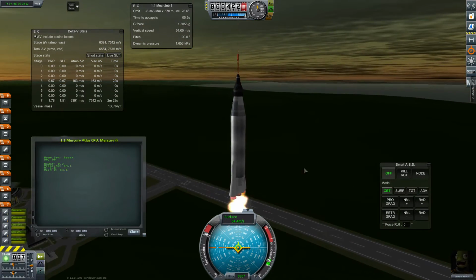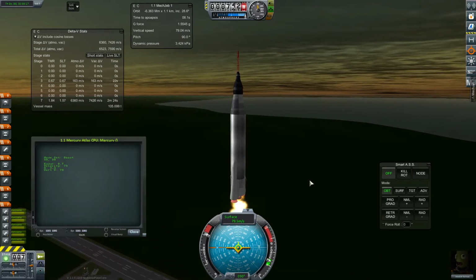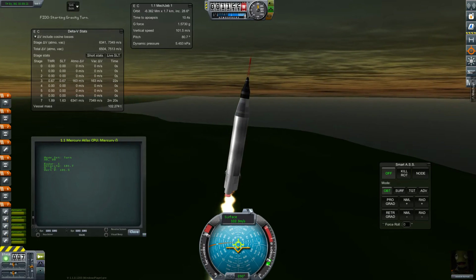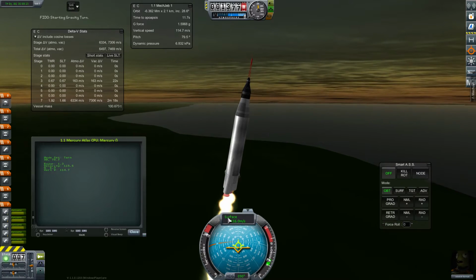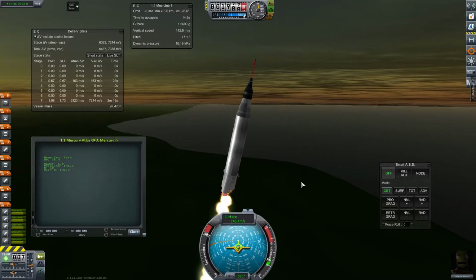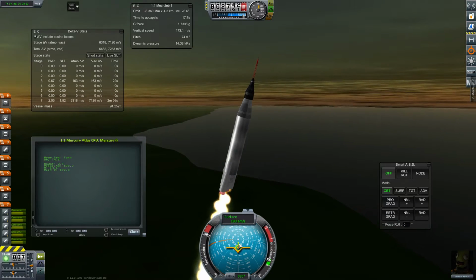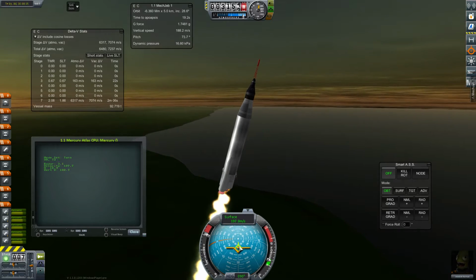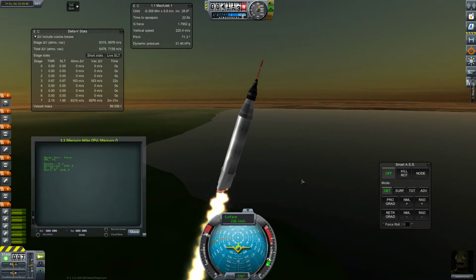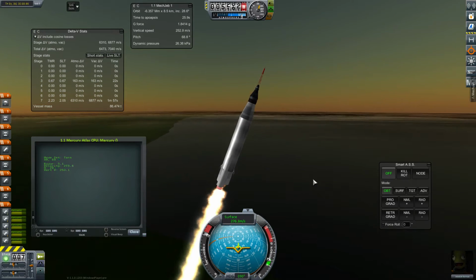It goes through a number of phases, and I'd like to get it down to two main phases, but there are always going to be these early phases, like straight up boost, and then the code has a line where it says, once you hit this speed, start your turn, start the gravity turn. From what I can see, the gravity turn doesn't have an equation directly, so it doesn't have a way to compare to your surface prograde, which will probably be important so that your dynamic pressure doesn't give you trouble.